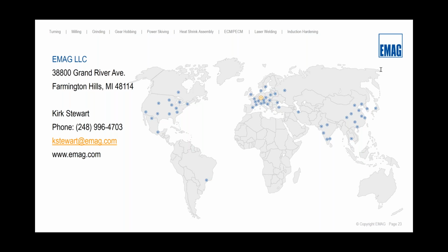And if you get something more exotic, let's say just for a keyway cutter, maybe you're spending 15 grand, whatever, for a live tool head. But if that eliminates the need for a broach machine and the broach tooling, I think you're ahead. So I would always challenge customers to think about combining processes that could be put on a live tool turret.